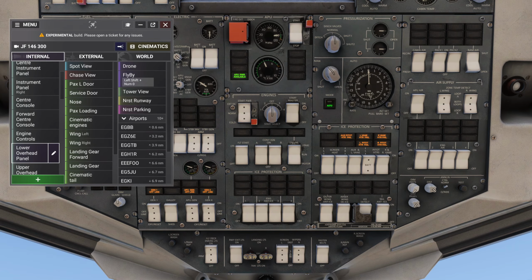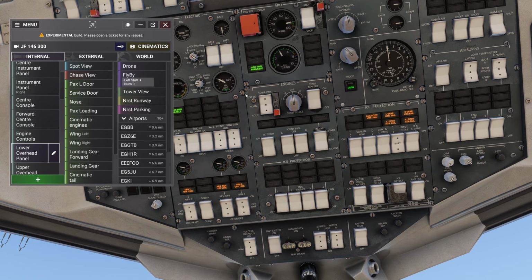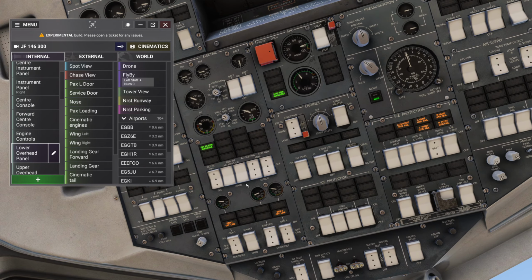APU is doing its thing. Absolutely. Let's keep going. Next, we can move on to ensuring that the APU generator is on and that we have proper AC power available. Once that's confirmed, we'll proceed with the next items on the list. Let me know when you're ready. Yeah, the APU generator is on green, so let's go. Continue.